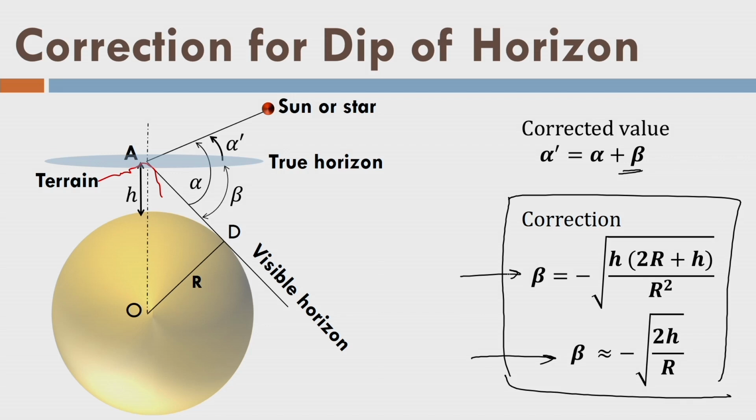Well, the height of the observer above MSL is much lower compared to the radius r. So the radius is in the order of 6400 kilometers, and the MSL height could in general be around a maximum of 500, 600 or maybe 1000 meters. The MSL height of Nainital is 2000 meters, and if you compare 2000 meters with 6400 kilometers, it is negligible. But if you go to the Himalaya or higher altitudes, it will be higher. Okay. So now we have put 3 corrections.